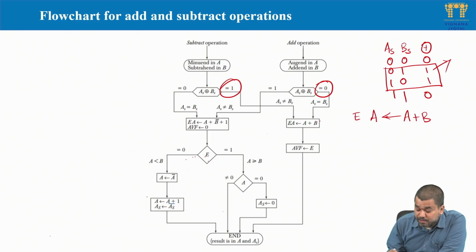These are the sign magnitude numbers. So in this case, if we are performing addition, there is a chance of having an overflow, right? Overflow here is indicated by the fact that E equal to 1. So if E equal to 1, there is an overflow. For example, if A is a 10-bit register and we get an extra 11th bit, that extra bit we cannot hold in A, so we say that we got an overflow.